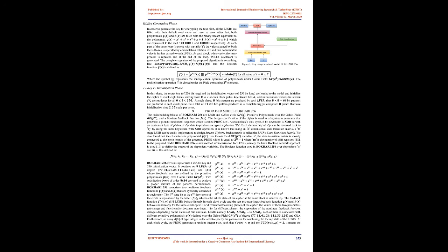The complexity and performance of the hardware correspond with other hardware-oriented stream ciphers like E0 and A5/1 and compare acceptably. [12] Grain is a synchronous stream cipher that operates on both an LFSR and a nonlinear filtering function. It adopts a bit-oriented architecture, which is appropriate for constrained hardware implementations that produce one bit per cycle. However, it also offers the option to increase its speed by increasing the length of the processing word. Grain provides higher levels of security compared with the well-known A5/1 and E0 ciphers while providing small hardware complexity.